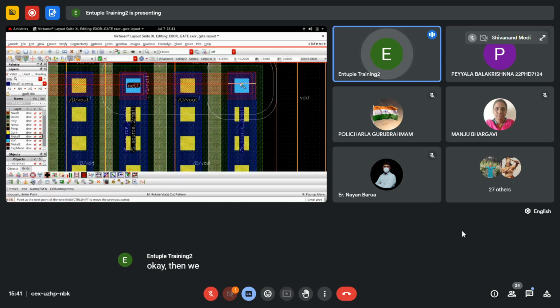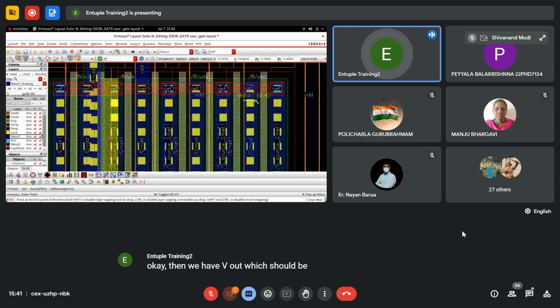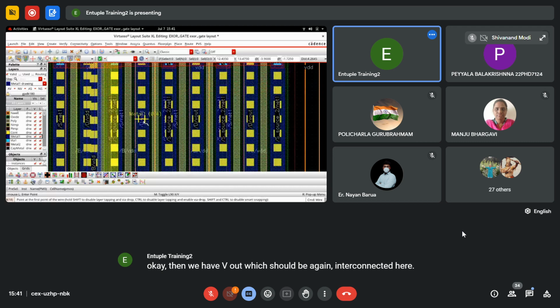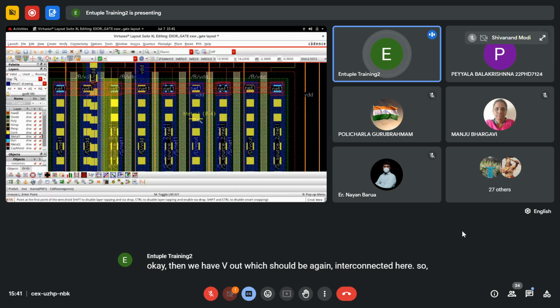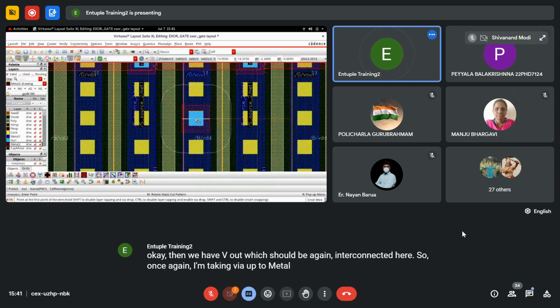Okay, then we have V out, which should be again interconnected here. So once again, I'm taking via up to metal 2.